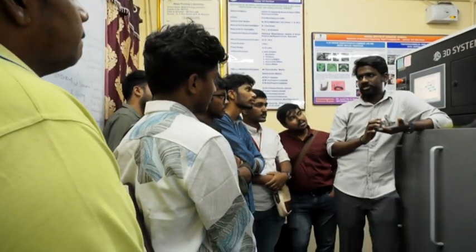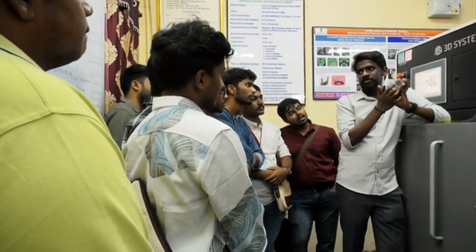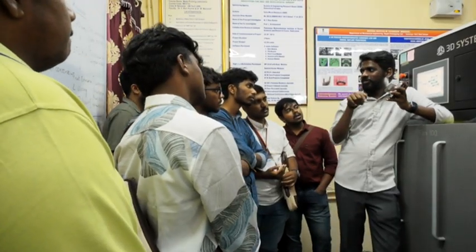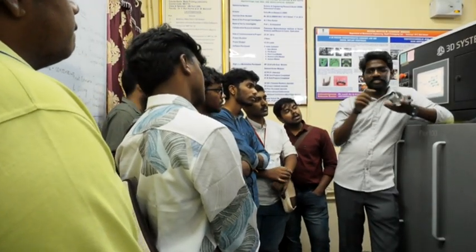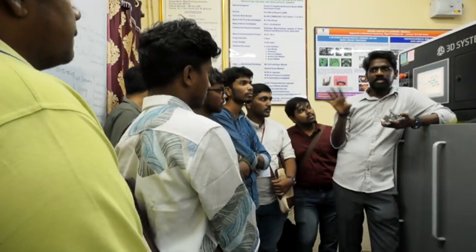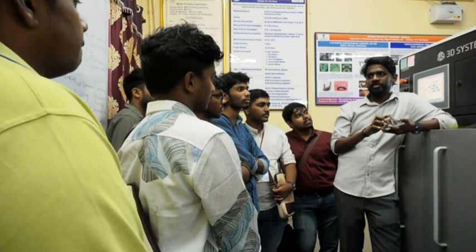Of course, sandblasting also you can use, but for these intricate shapes you can't use sandblasting because the flow doesn't go inside directly, as it has curvature. Okay, that's a problem. So it is better to use an ultrasonicator. So that is also one of the post processing techniques.